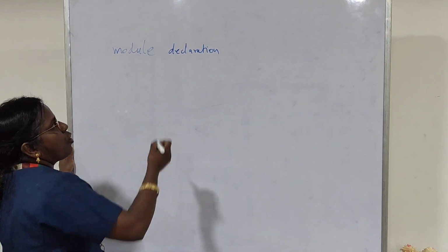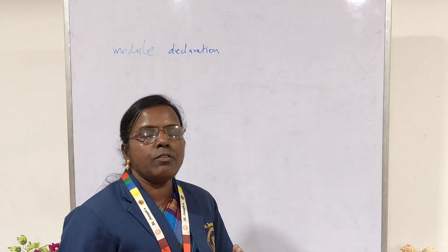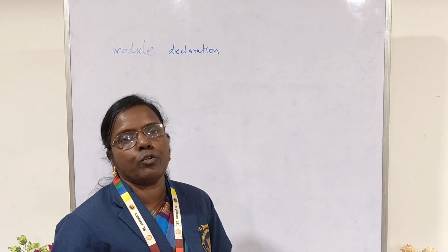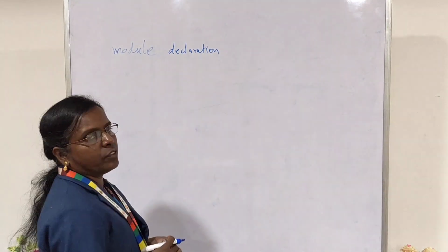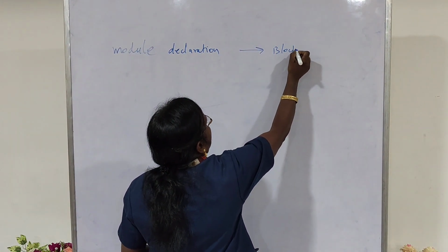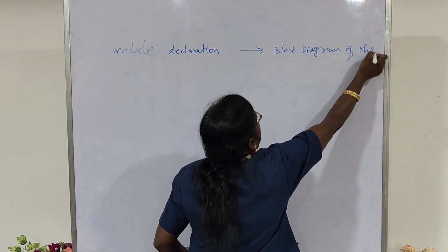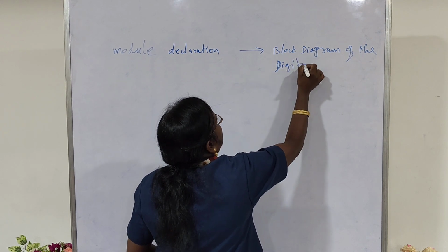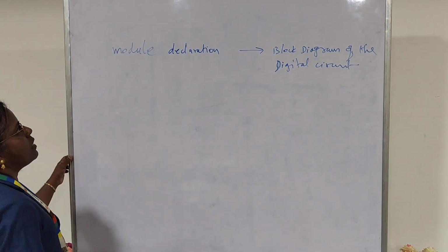This module declaration consists of the keyword module, the name of the module, and the input and output port list. Input and output signals are listed in this first part of the Verilog program. This is basically the block diagram of the digital circuit, described as the module declaration.